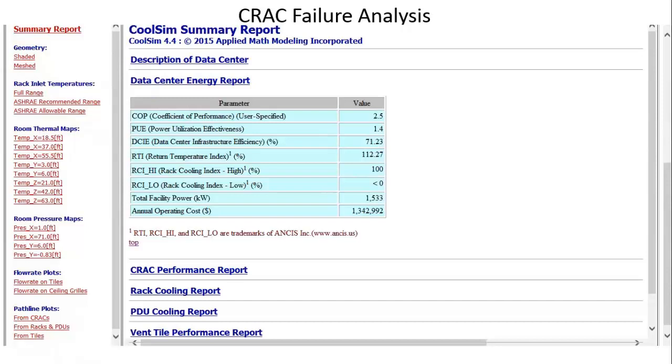And this is why, again, I point out that you can't have perfect seals on your hot aisle, cold aisle. It's actually better to let them leak just a little bit because you don't run into the pressure problems that sometimes can occur when you've got a perfect seal of hot and cold. Well, sometimes we've put tiles with dampers to modulate the airflow in the hot row. Yeah. Just to be able to help circulate air.